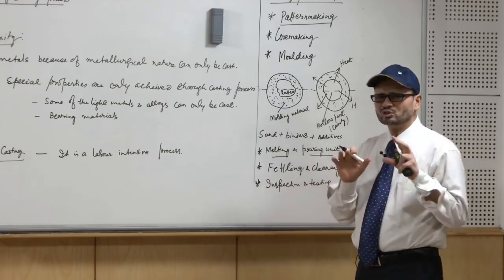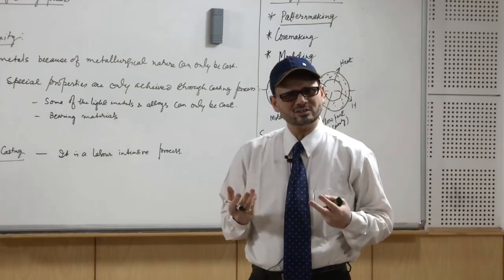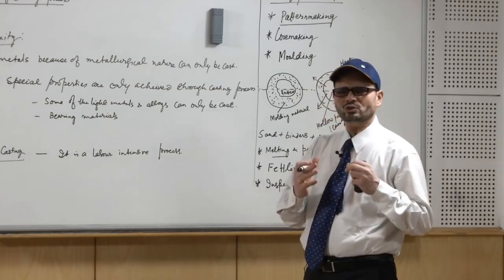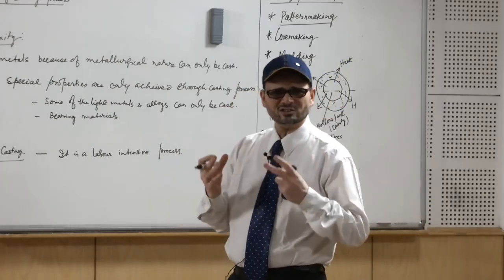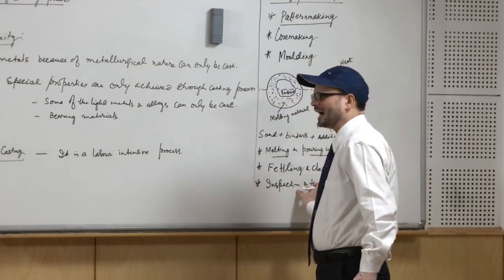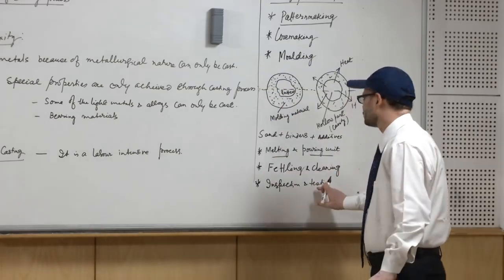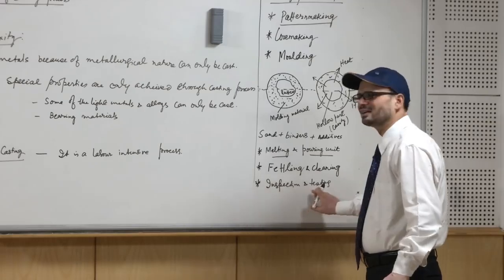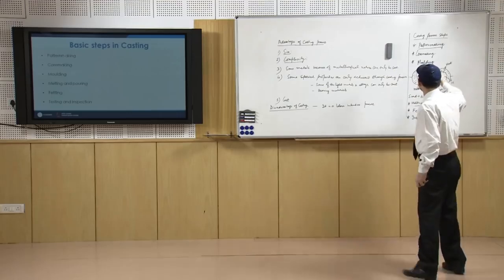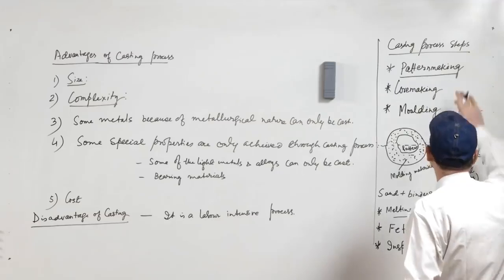So, for that it goes to the quality control section, where you have different type of testing units, like you have magnetic particle testing, you have use of different type of rays. So, all these things are carried out either on all units or on the critical units, and by also sampling you do this inspection and testing, and finally it is sent to the customer. So, these are the normal steps in the casting unit,